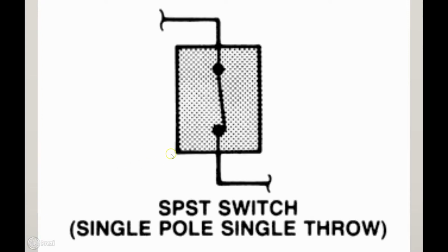When you draw a circuit for me in automotives at SECHS, you're going to draw it similar to what you see here. There will always be a box around the switch, and you'll see where current comes in through a conductor into the switch. This is the arm that can move back and forth, and you'll also show where current can flow out of the switch, where current flows in through the switching device and then out through the switch. So this is called a single pole, single throw switch.